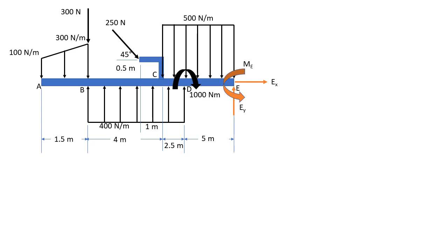Before we solve these forces in class, take note that we first move this 250 Newton force to point C, because that is how we will determine the full effect of the 250 Newton force in our beam and not just in the hanger.